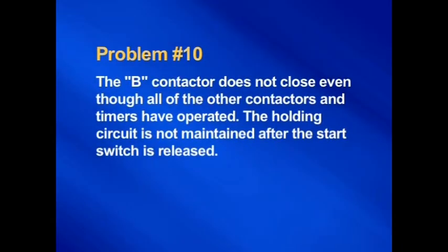Problem number 10. If the apprentice draws this problem at the testing center, it'll read as follows. The B contactor does not close even though all the other contactors and timers have operated. The holding circuit is not maintained after the start switch is released.